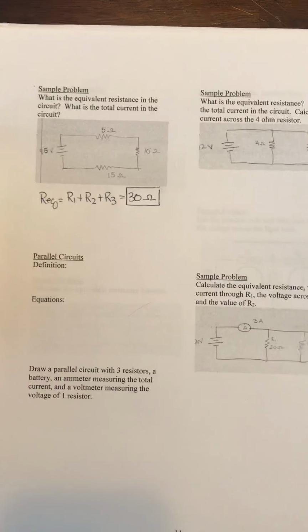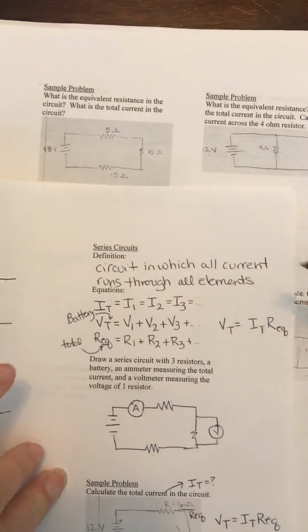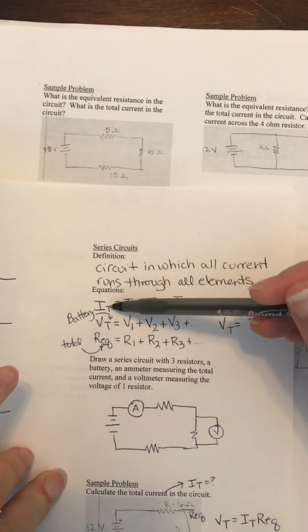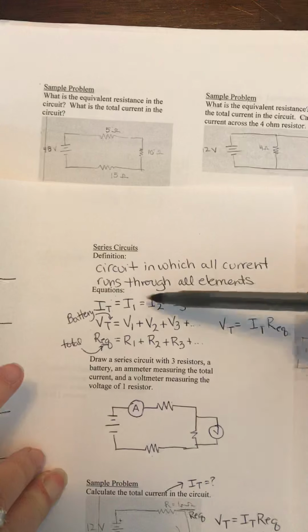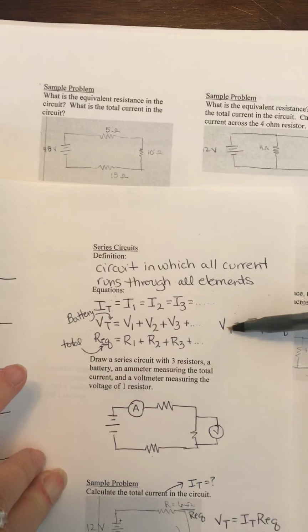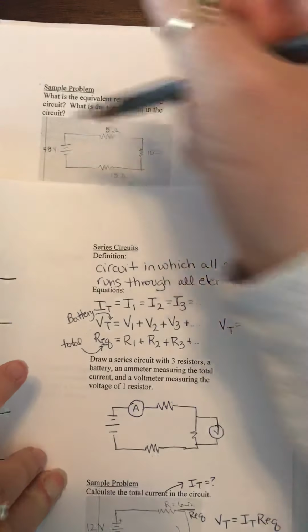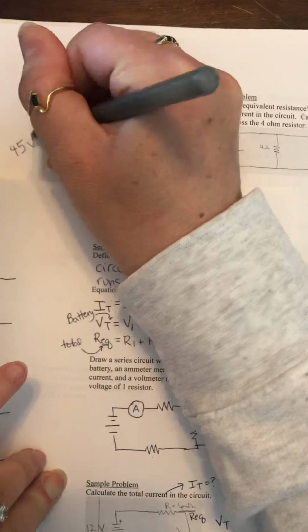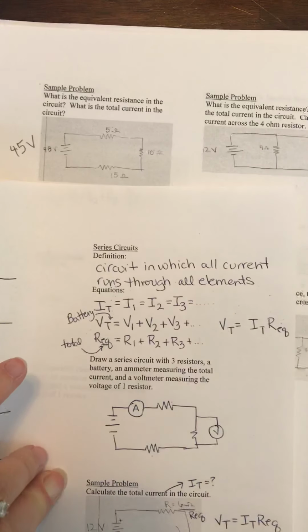And now when I'm looking for the total current in the circuit, if I look back at my formulas here, there's really these 2 equations to find the total current. This one or that one. So hopefully you're saying to yourself, we don't know the current in any of these pieces, so that's probably not a good choice. But we do know the total voltage, right? Because we have the voltage of the battery. In this case, hopefully you can read this, that it is 45 volts. We just calculated REQ, and then we're finding IT.